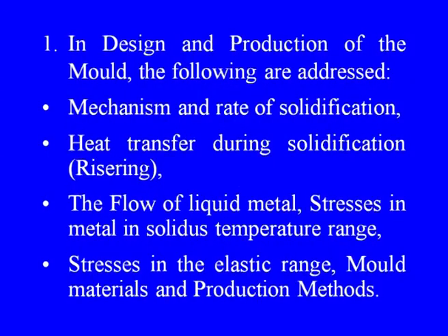Now, let us see the casting problem. The casting problem can basically be divided into two areas: number 1, the design and production of the mold, and number 2, the melting, refining, and pouring of the liquid metal. In design and production of the mold, the following are addressed: mechanism and rate of solidification, heat transfer during solidification, the flow of liquid metal, stresses in the metal in the solidus temperature range, stresses in the elastic range, mold materials and production methods.